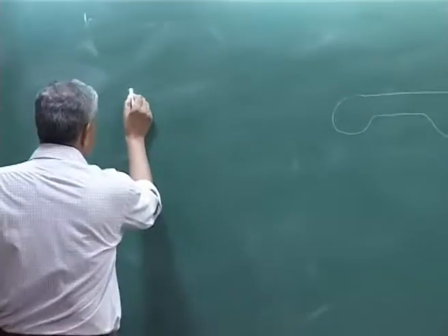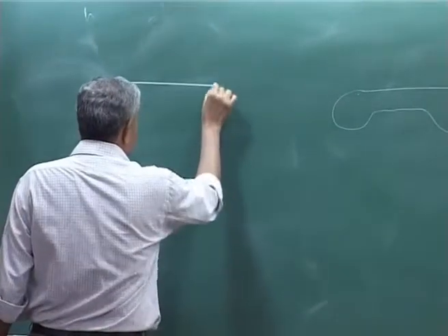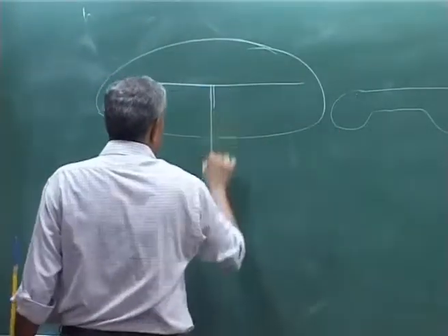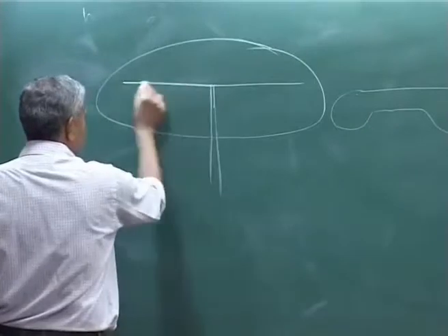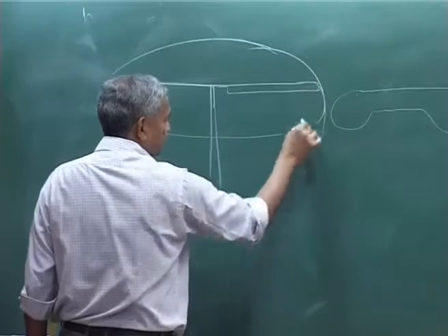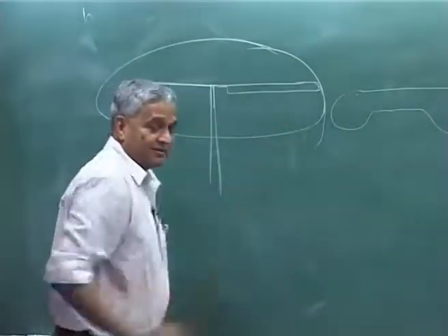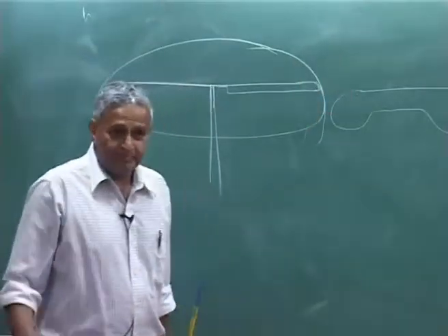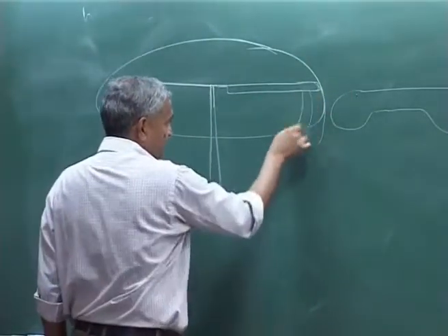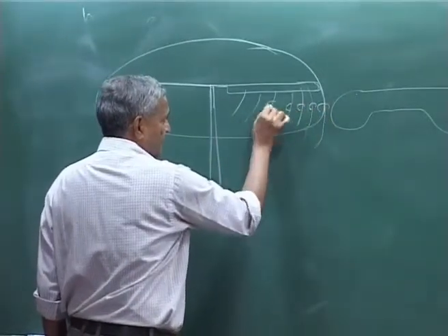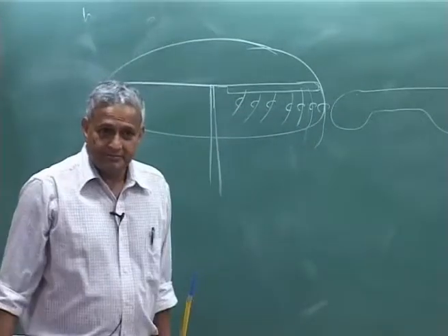Okay. Because if you start looking at the vortex theory as such, if I draw this as the rotor, this is the shaft, this is the rotor, it is rotating. The vortices will be, because as it goes, you will find a vortex coming, and if the lift is varying along, you will have a vortex sheet actually. A sheet will come,